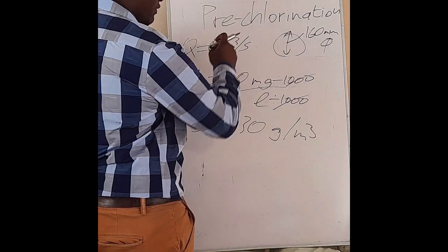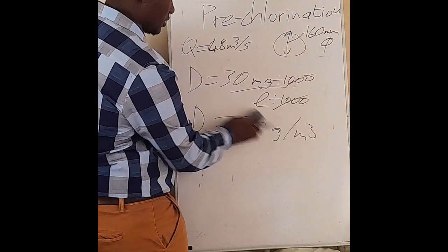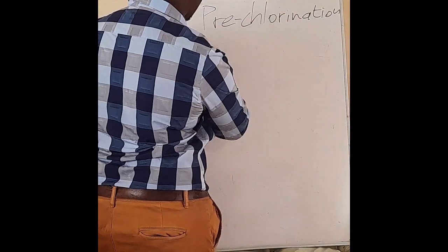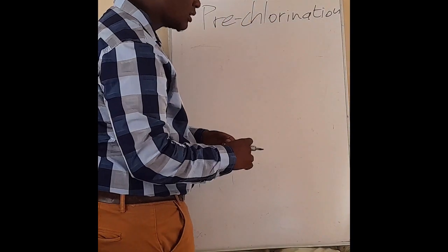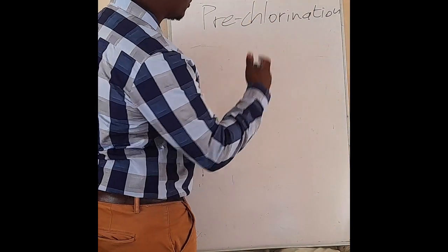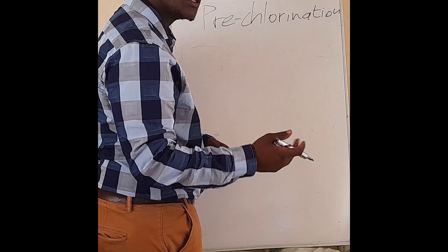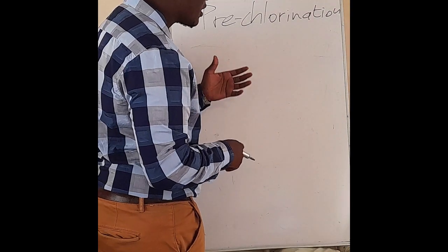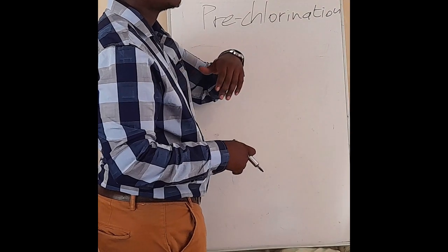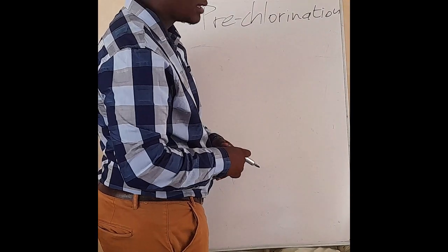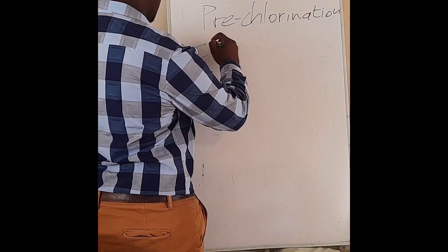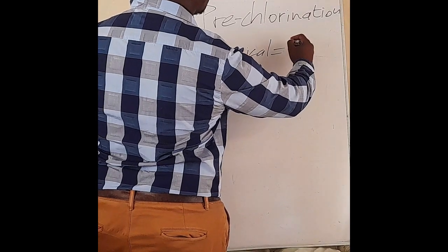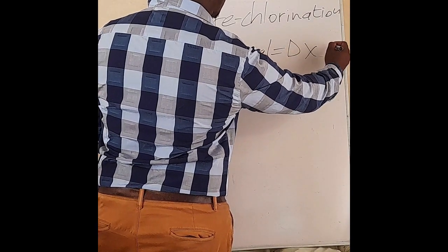We now have our dosage, also have our flow rate. Okay, so just rub that off, and now we'll calculate the amount of chemical needed in order basically for chlorine to work at its best, so that you can control the amount of algae and basically try to disinfect the water at an earlier stage, as much as it will also be disinfected right at the end. So basically, let's say the chemical that we want equals the dosage multiplied by our flow rate.